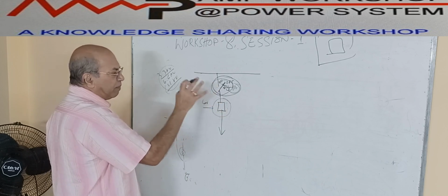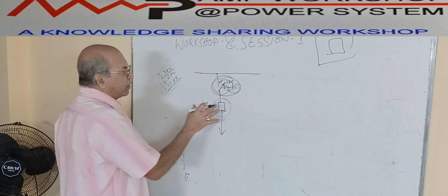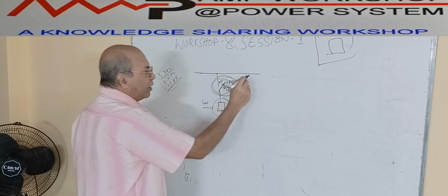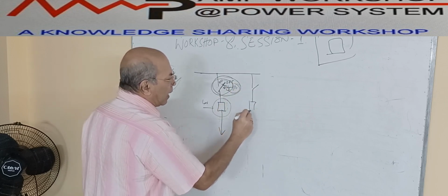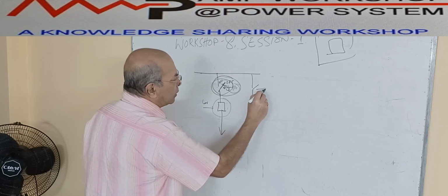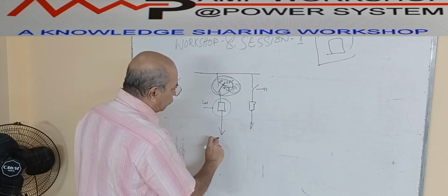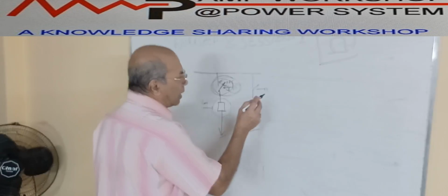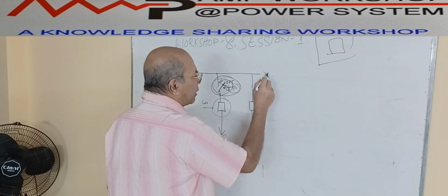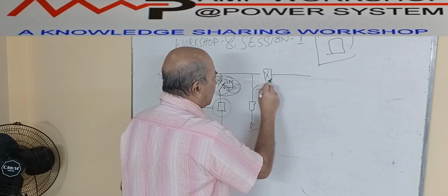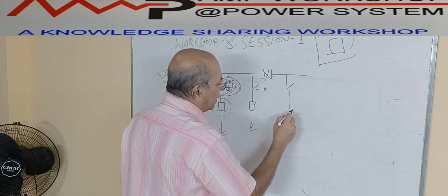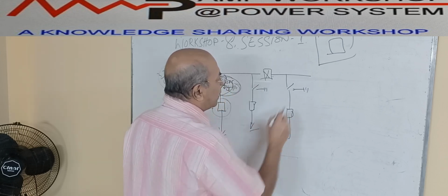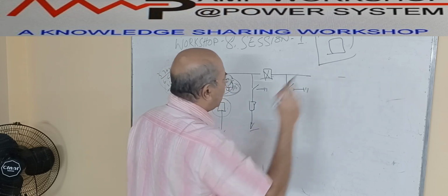This is the case of fixed type switchgear or GIS switchgear. We need these arrangements. In case of a single busbar arrangement, it will be like this. Each feeder has one isolator, and the isolator has the earth position, and it is going to, suppose, a generator or a remote feeder like that. But if we go for the single busbar with a bus section arrangement, suppose this is a bus section breaker, then here also the same thing will be there. This is the isolator with an earth switch, and there will be a disconnector over here. The breaker will be here. Similarly, this will proceed.